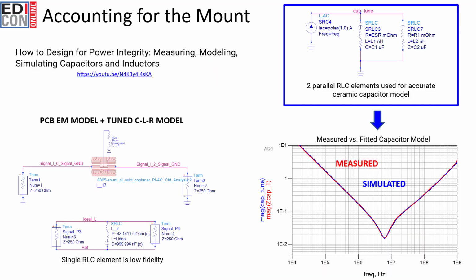So how do you account for the mount? If you will be using the S parameter measurement for simulation, perform the fixture removal calibration using a short that is as close as possible to the capacitor dimensions. Then measure the capacitor and export the result for simulation. That will result in the 144 picohenry inductance difference that we showed previously.